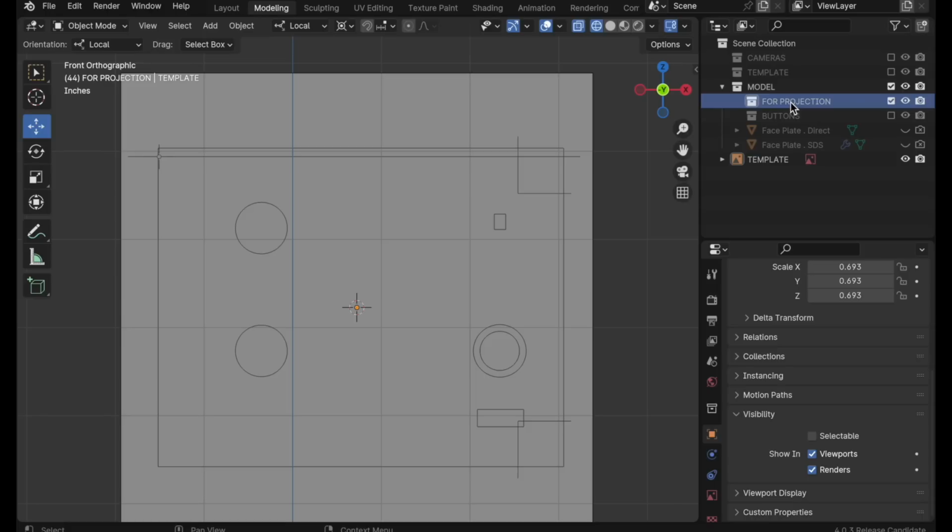We're going to use the knife project tool to do this. We're going to be relying on the fact that we have a large planar region with these cutouts in it. One thing to keep in mind is that polygons don't like to have holes in them. Applications like Blender have to perform tricks to make it look like you've got a hole in a polygon. So let's approach it with that understanding in the back of your mind.